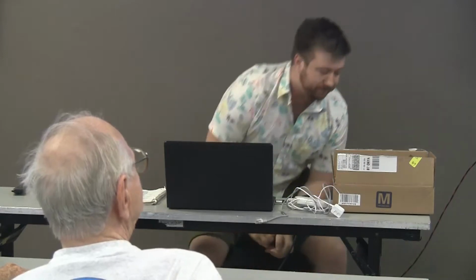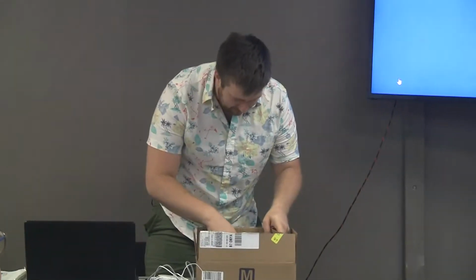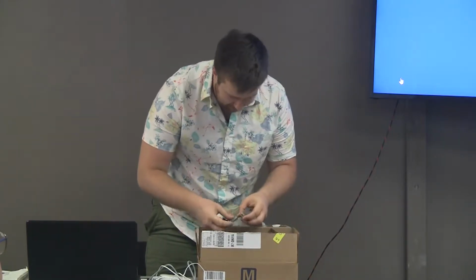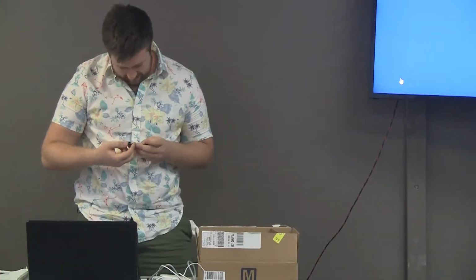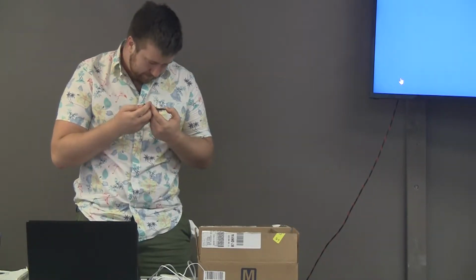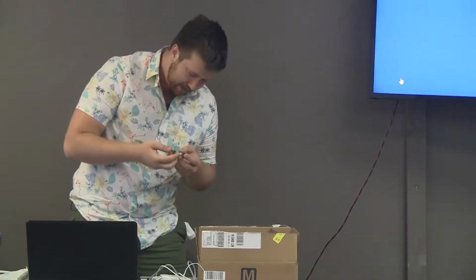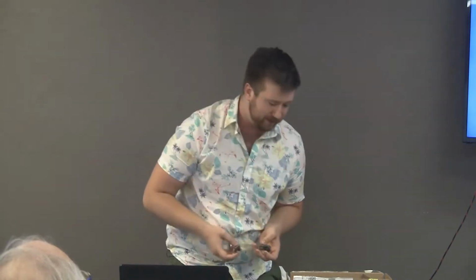Okay. So now Z-Wave. Oh, wait a minute, before you leave Bluetooth, what module would you recommend if you were Arduinoing now? If you're Arduinoing, I would say just don't even use a module. I would use something that has an ESP8266 on it already, and use one of those. I have two from Adafruit right here, the Feather series, the Huzzah and the Bluefruit, I believe. These are Arduino compatible, you just have to download the library specifically, and have the Wi-Fi all built in.